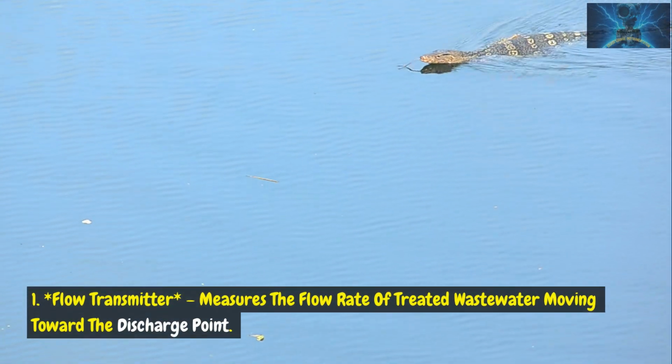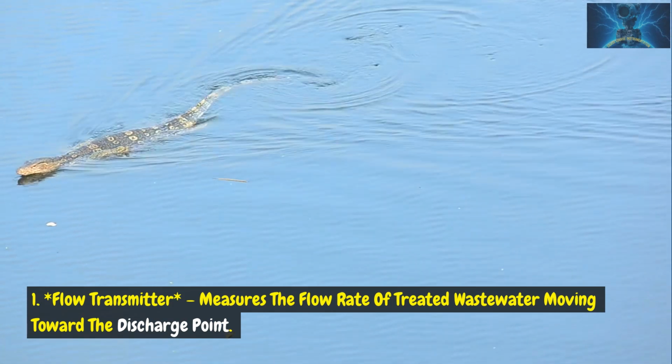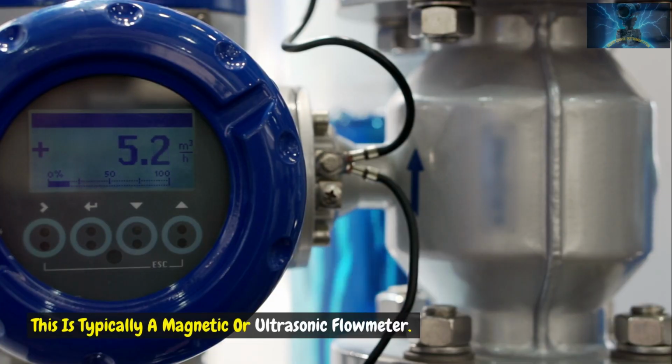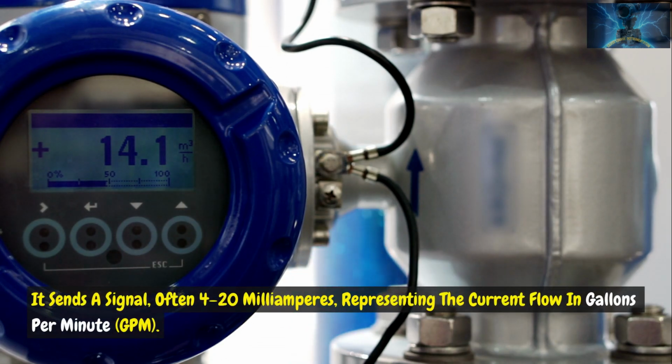1. Flow transmitter. Measures the flow rate of treated wastewater moving toward the discharge point. This is typically a magnetic or ultrasonic flow meter. It sends a signal, often 4 to 20 milliamperes, representing the current flow in gallons per minute, GPM.